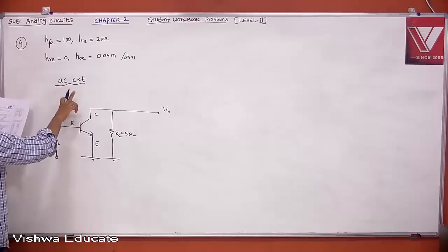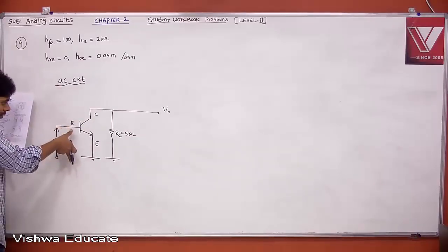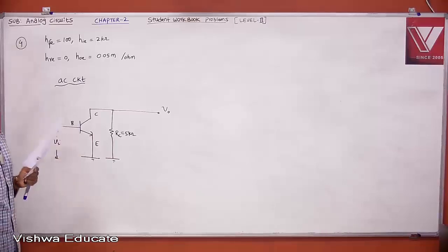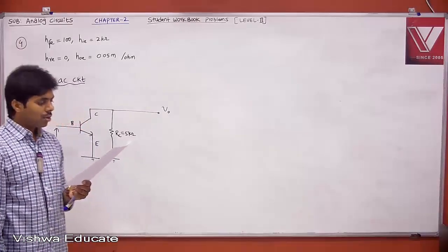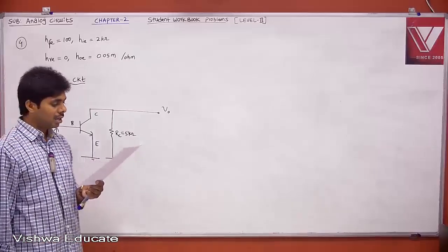Then this R1 is coming in parallel to R2. That is coming in parallel to your input voltage. A voltage source in parallel to a resistor is nothing but a voltage. Therefore, you can ignore that R1, R2 combination for AC analysis. That has significance in DC analysis. Okay.